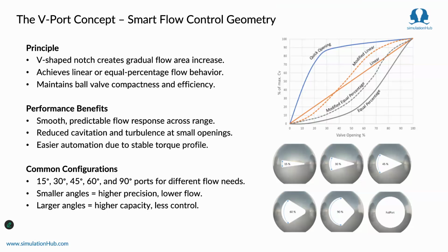What it adds to the conventional ball valve is that your CV is much more controlled and much more predictable. As opposed to a full port ball valve, you can have a better prediction of your CV, depending on the notch angle and the notch dimensions. The images show a standard size of notches that are usually used, but you can even customize these notches.